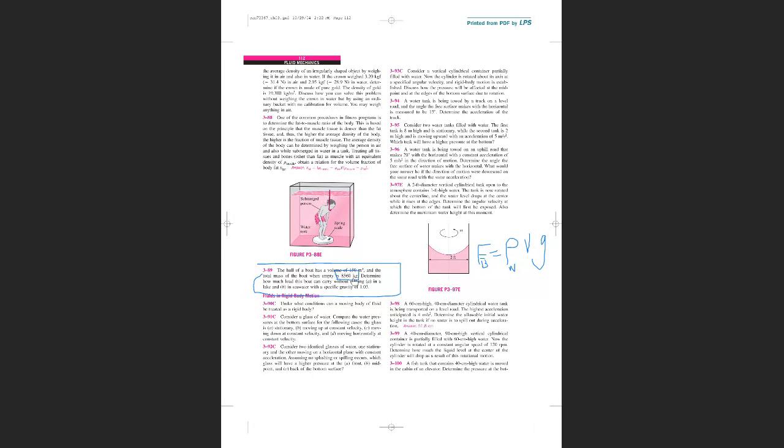Yes, right. So basically you calculate the buoyancy force, and then you subtract the weight of the boat, and that will be the maximum extra load the boat can withstand. And it differs, by the way, because rho differs from seawater to a lake, fresh water. Once rho is 1000 and once rho is 1030 kilogram per meter cube. So that is the idea of 89.